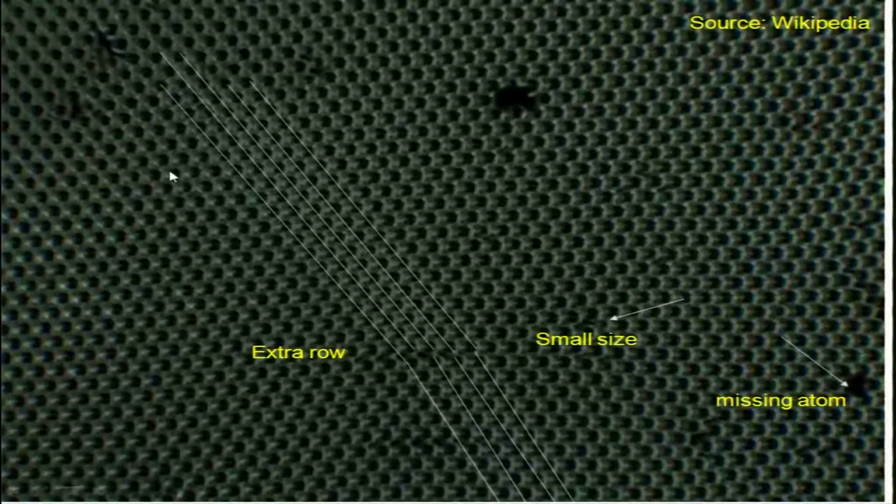You can see that astonishingly they look as if you have a bunch of atoms, but when these atoms come close to each other, they are not perfect. The arrangement of these atoms is not perfect. For example, you can see a small bubble sitting here. It is like a small impurity, an interstitial atom. You have a missing atom here on the right side, okay. Now let me use a pen. So, this is the missing bubble, which is like a missing atom.